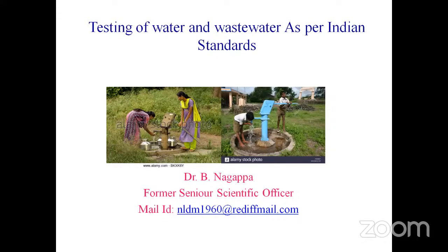Durability means it has to perform according to the lifespan designed for the concrete, because otherwise concrete will deteriorate. Even the previous speaker, Krishnamurthy sir, clearly mentioned the deterioration of concrete due to physical action, chemical action, and mechanical action. See, one of the chemical actions is due to the salts present in the water. Therefore, before using water for concrete making, we must select good quality water. IS 456 clearly mentions potable water. The water used must be potable to make concrete, then only is the concrete durable.